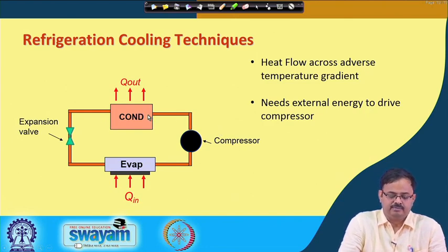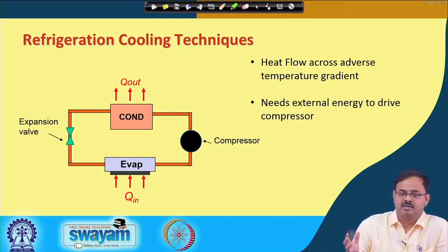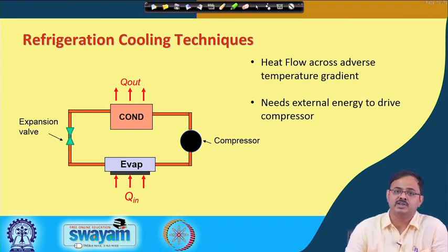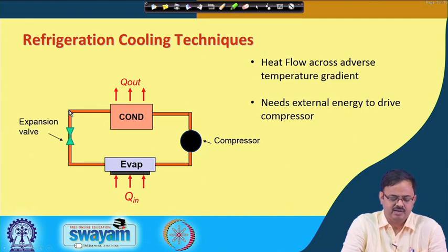and then the heat is extracted in the condenser, which typically is situated outside the main refrigerator chamber or in the outside unit of your room air conditioner. So, what comes out of the condenser is again refrigerant liquid at high pressure and therefore high temperature as well, typically ambient temperature, outside ambient or slightly higher.